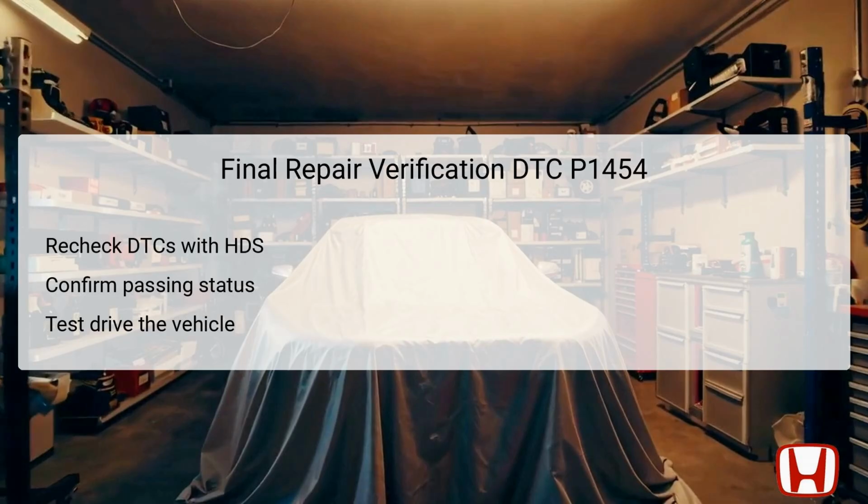Start by rechecking for any DTC codes using the Honda Diagnostic System, HDS. It is essential that the system indicates a passing status with no errors present. Following this diagnostic confirmation, a thorough test drive of the vehicle must be conducted to ascertain that the repairs have restored normal functionality to the EVAP system.